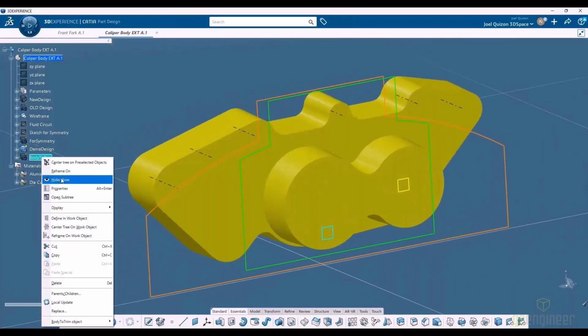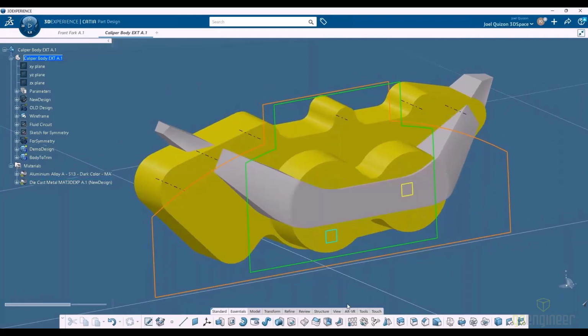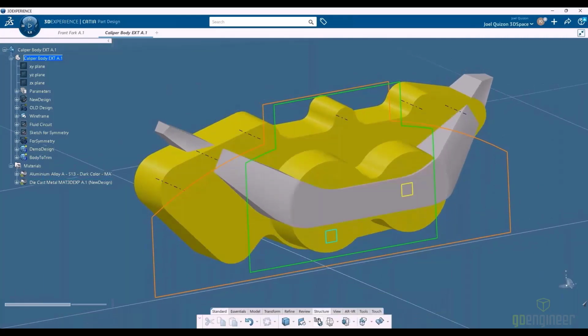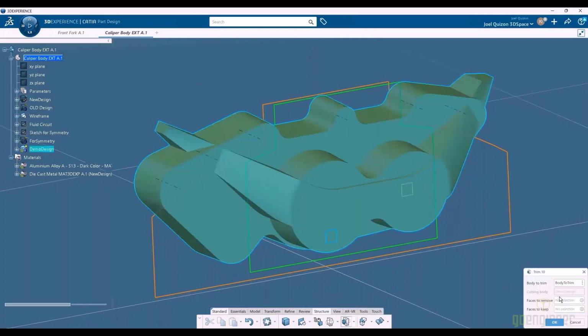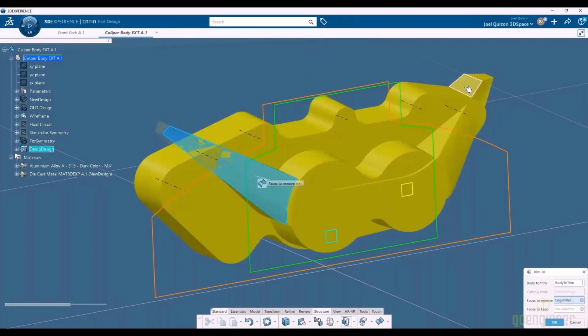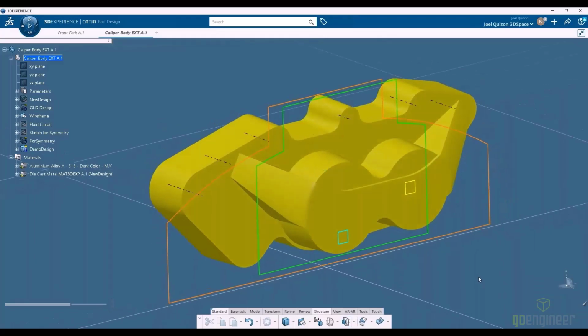Now, I already had a body that was already created. I'm just going to show that. That's a separate body, but I could go in and define it, set that up as a union. It's called a union trim. So it's kind of nice. I'm able to just select the faces to remove quickly, and it removes that portion of that model.